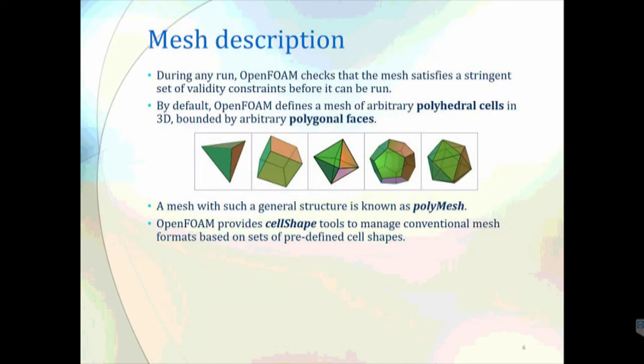So starting off with the mesh generation and conversion. Mesh, as I described briefly last time, is just a method to define your problem, to define the physical dimensions of your problem and to represent them using equations. In order to represent your physical dimensions using equations, you have to break up your actual physical volume into a mesh, which is basically a collection of nodes. As you can see, there can be different types of mesh.